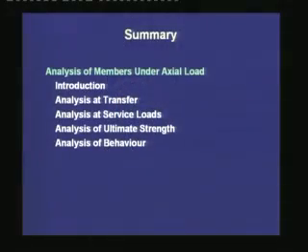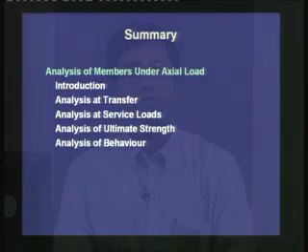A member can be either fully prestressed, where we do not take account of any non-prestressed reinforcement for the strength, or partially prestressed, where we take advantage of non-prestressed reinforcement also. We studied the analysis of ultimate strength, where we found out the maximum capacity of an axially loaded member. It can be either the tensile strength or the compressive strength, and this strength has to be larger than the demand that comes from the external factored loads.